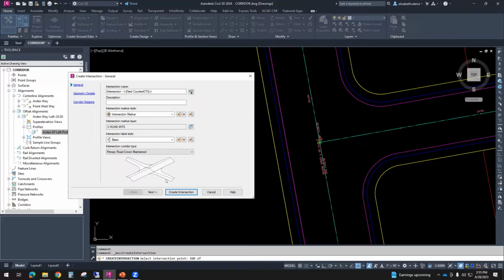And then maybe you have these smaller arterial streets that intersect with it. These will come down to join the low point of the main road, and then come back up to the high point and down to the low point and then out, right? So we're actually bending the profile of these crossing streets to match the shape of that main road, because you probably have a stop sign. So it's not like you're speeding through that bump. You stop and then you slowly come back up and over.